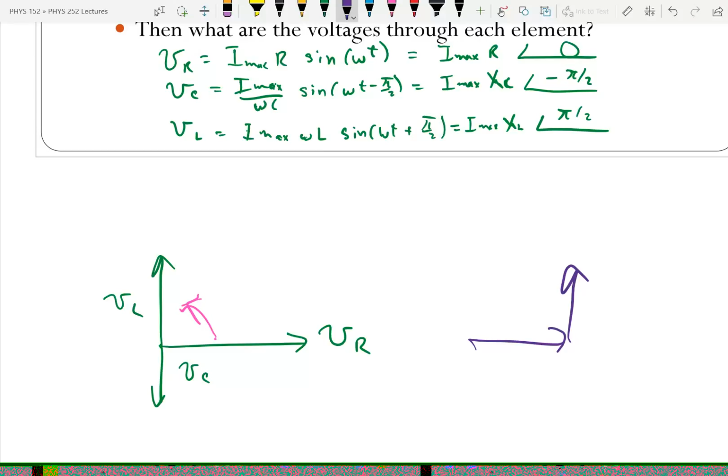But with that iron core, you have to rotate the domains. That takes energy. So there is energy lost in a real inductor because of the work to rotate the domains, and that's what we associate with resistance. So there's an effective resistance to the inductors. Capacitors are pretty much ideal, but the inductors have an effective resistance. So when you do this, you're going to find a little bit of resistance in the inductor that comes from that internal resistance.